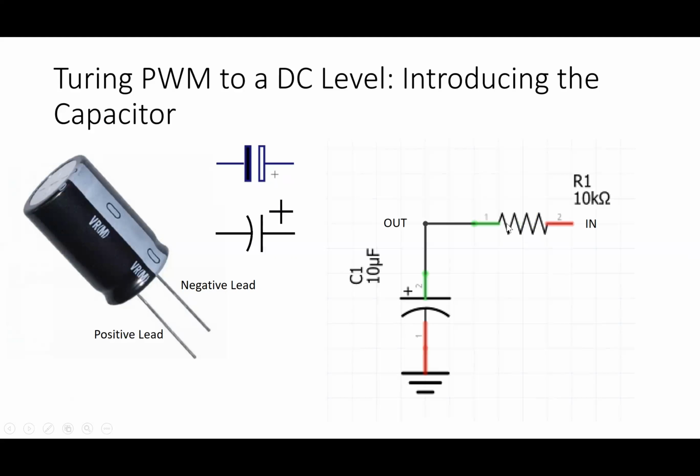And what a capacitor does is to store a lot of charge. So 1 microfarad turns out to store a microcoulomb for 1 volt applied. If you put the charge in and out via a resistor, so the flow of charge is slowed, then providing the response of this resistive and capacitive circuit is much slower than the input waveform here, and don't worry, I'm just telling you stuff that you will understand in much more detail later in the course, then this time varying waveform here, just as it was averaged by our eyeballs, will be averaged by the resistor and the capacitor to give us a smoothly changing DC level here.